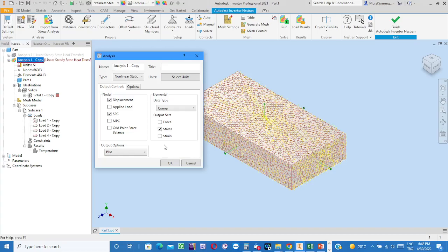It is to say that the stress value is 3 times smaller than the yield limit, 2 times smaller, n times smaller. Okay. But in the plastic region, the important thing is whether the stress is less than the tensile limit. Okay. Ultimate stress, less than the ultimate limit.